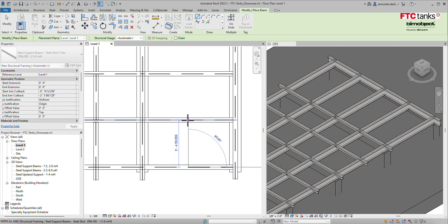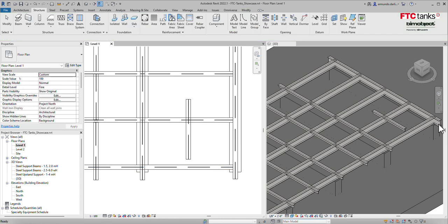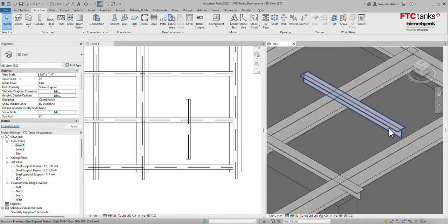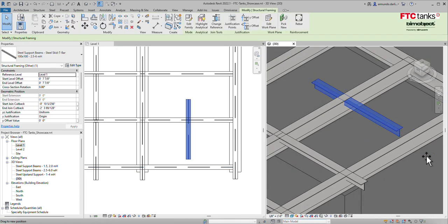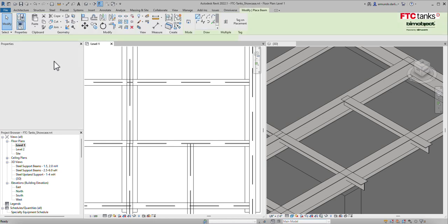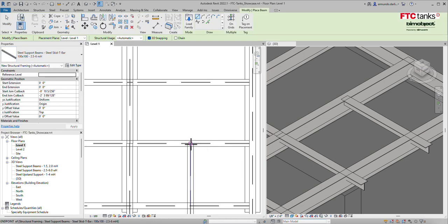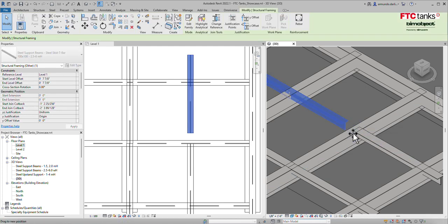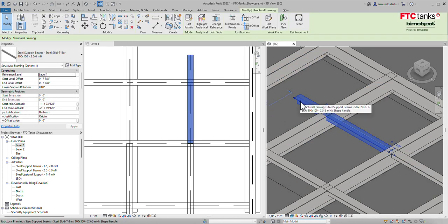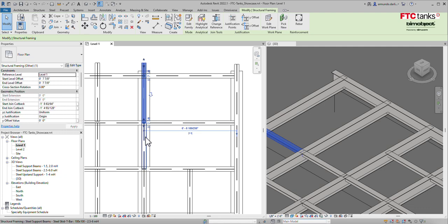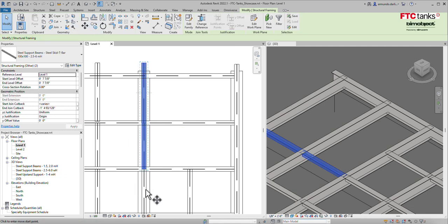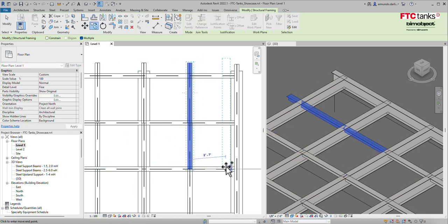If you copy the sample models into your project, you can right-click and use the Create Similar tool to model a T-bar beam. To adjust the beam, use the grips to model the T-bar according to your design. You can also access the T-bar using the Beam tool. Then model and adjust the T-bar as needed. And of course, you can copy and paste them once you've already placed them into your project design.